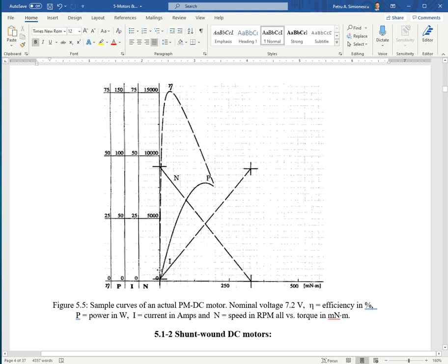The first is the RPM axis. So torque versus RPM would be this curve. Then we have torque versus current. This is the second y-axis. So you can tell some performance parameters. What would be the maximum RPM? What would be the maximum current, the stall current?